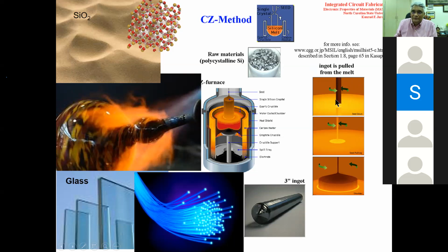when you start pulling it up, the temperature gradient is created, and sometimes the cooling rates have to be as low as 1 degree per hour, 0.5 degrees per hour, and there should not be any variation in the temperature, the rate of cooling. If there are variations in the temperature, that can lead to strains in the single crystal that is formed there. That's why I said single crystal growth is a very expensive and also tedious process, because you make this 5